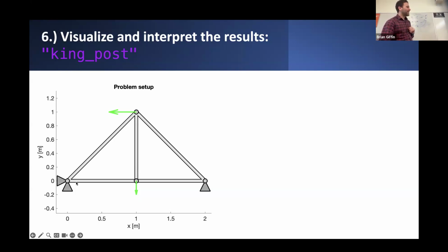So how are the forces defined? How are the boundary conditions defined? So you can verify that everything was defined correctly. It looks okay. You can also visualize the coordinates of the nodes, make sure they're positioned correctly and the connectivity of the elements.